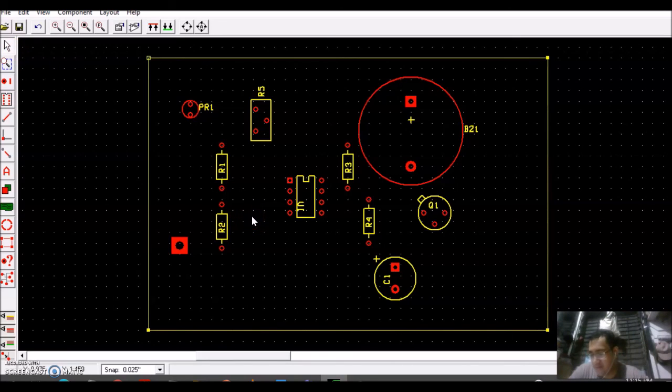Create another pad, this time using description 0.150 round pad with 0.079 hole near the first pad and assign it to pin 2. Then select both pads, group them together to make a component. Label the component with the part ID B1.